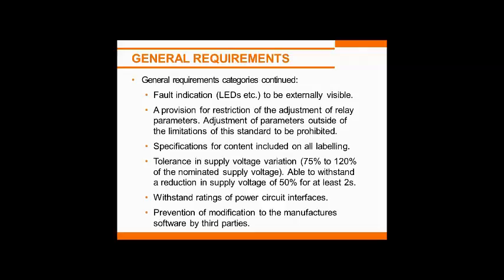There are some specific requirements. Parameters should not be able to be set outside the limits of the standard. So, for instance, with earth leakage at the moment, the common maximum setting for a time delay is 500 milliseconds, whereas in previous standards you could go out to 1 or 2 seconds. We're now restricted to keep the relay so that it cannot be set anywhere outside that limit. Now that can be done two ways, either these days more likely with a password, or you could physically lock and stop people getting in to make those adjustments. And that's how that's done.